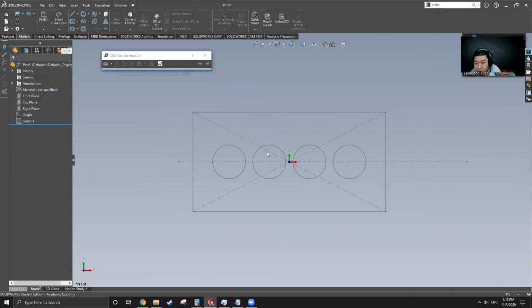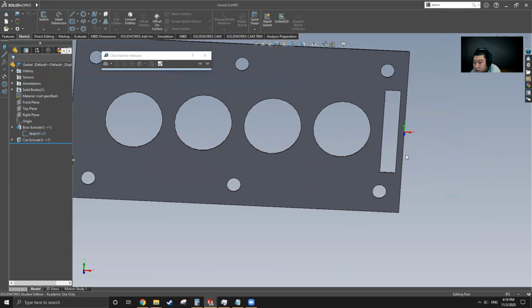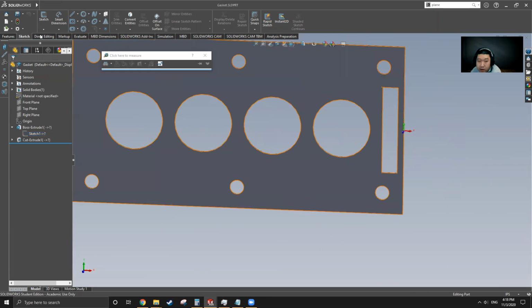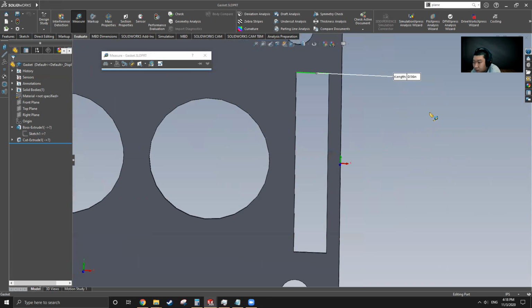And one more we can add to it, this vertical rectangular hole, which, let's measure, is 0.56. Same thing with the 0.06 tolerance, because initially the hole on the engine body is 0.5 by 3. So now we're going to add an extra 0.06 as tolerance. So 3.06 and 0.56.